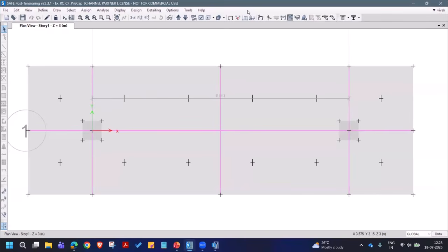Yes, for this slab definition, you can use the shell thick, which includes the shear deformations. Right? So, as per the code also, we are required to include shear deformations always. It will not be significant, but still, being a thicker slab, the footing or the raft, can use shell thick for the slab property definition. The strip area, the default definitions in property modifiers used within the program are sufficient. No need to modify unless there is a need, then do it.